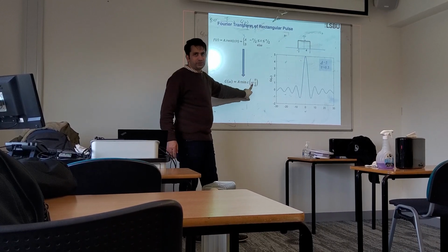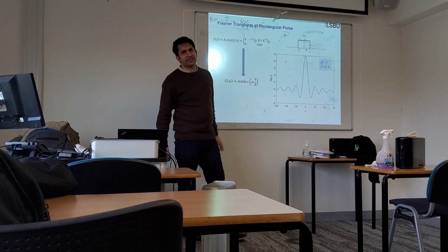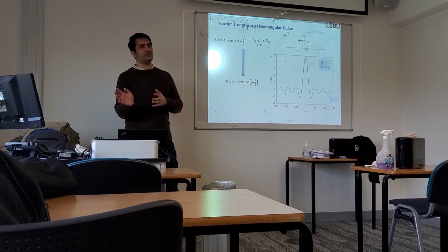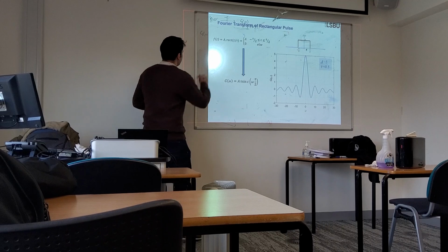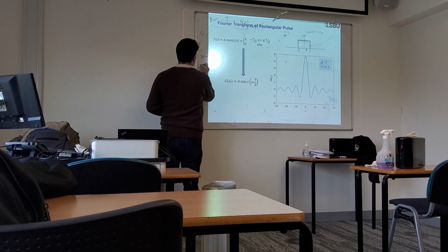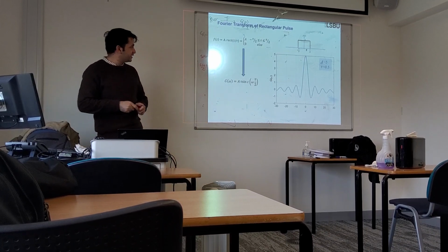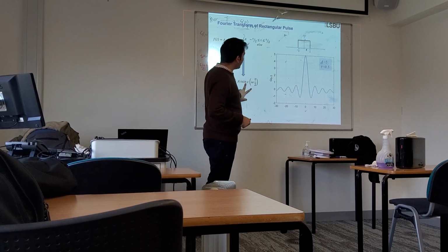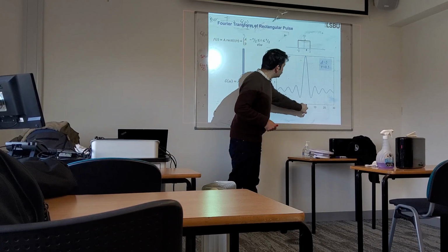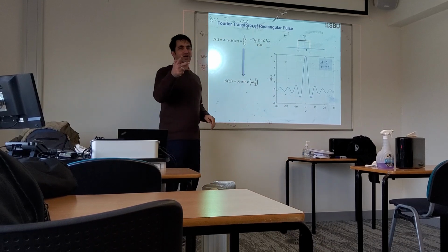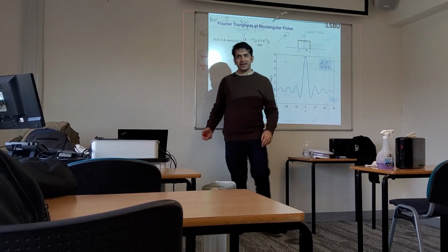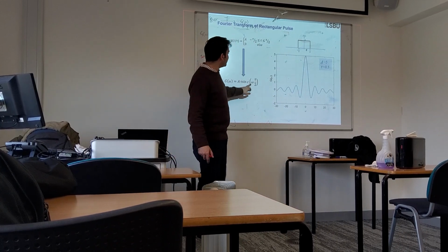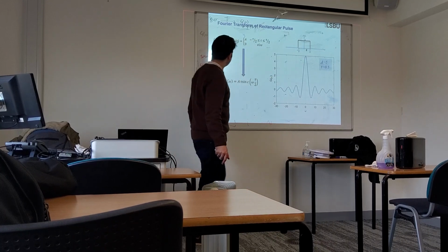So if we put omega equals to 0, so sinc of 0, this is an identity, there is a proof for that, but sinc of 0 is 1. We know that sine of 0 is 0, right? But if you have sine of 0 by 0, this is 1. This is a mathematical identity. So it means that sinc of 0 is 1. So that's why you can see that at 0, you have maximum value. And for that maximum value, you asked a question, what is tau? So now we can choose different tau. You can see that here it is plotted for tau 0.5 and A is 5. So based on that, you will get your value as 5.